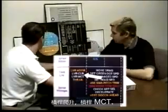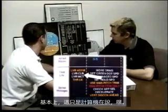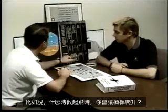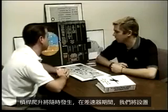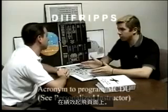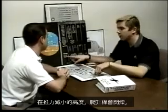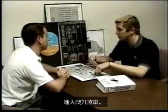Lever climb, lever MCT. Describe those for me. Basically, it's just the computer saying, hey, you need to move the thrust levers to the specific detent. In most cases, we're seeing lever climb. When would you get lever climb, say on takeoff? Lever climb is going to occur during the performance takeoff page, where we're going to set the thrust reduction and acceleration altitude. At the thrust reduction altitude, lever climb is going to flash, reminding me to move the thrust levers from either toga or flex into the climb detent.